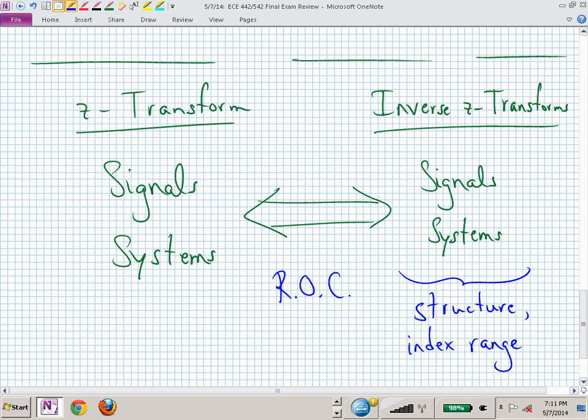If you don't remember, go back and look at the Z transform definition, and that's going to basically say I cannot have negative indexed time domain signals if that point is in my region of convergence. So that corresponds to causal sequences, positive time indexed n, because there you have z to the -1, z to the -2 being weighted.